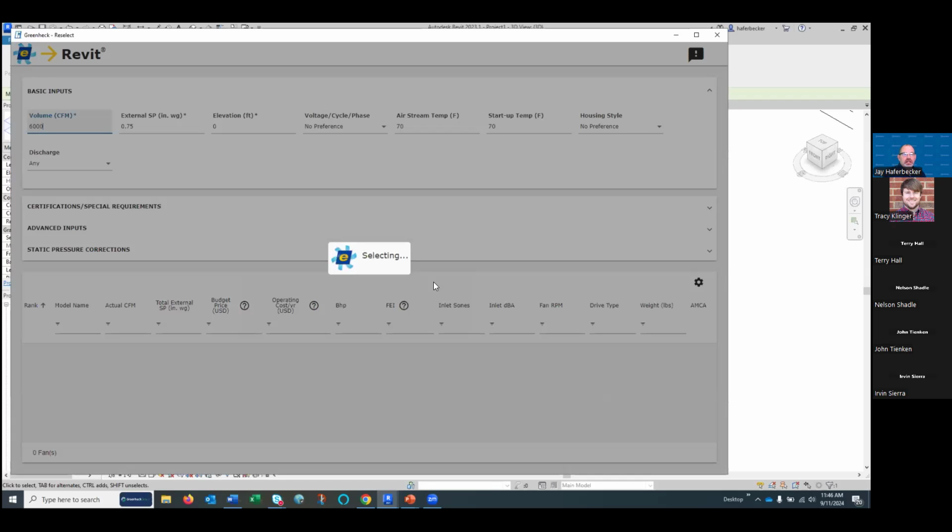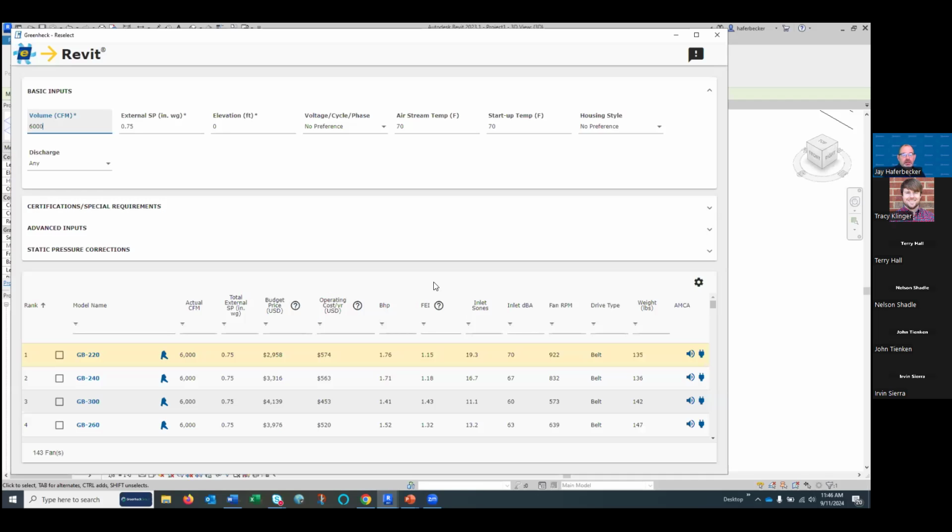And it's going to reselect this thing and re-highlight the original row that I had selected in my grid. And then from there, now we can modify it. So once this thing, which takes about 8 to 10 seconds to do here, is done, what we can do is come on here and say, well, now I want to add 500 CFM more.